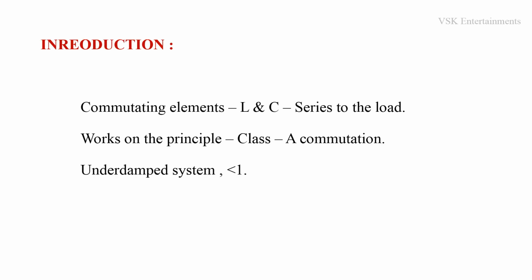Coming to the introduction, a series inverter is an inverter in which the commutating elements are connected in series to the load. Here the commutating elements are energy storage elements, that is, inductor and capacitor. The inverters in which inductor and capacitor are connected in series to the load are called series inverters.